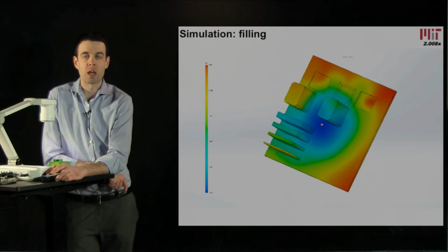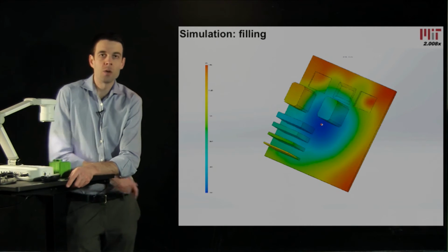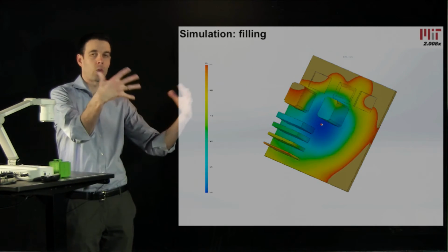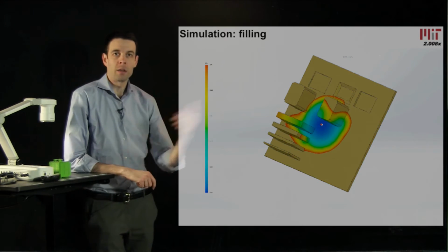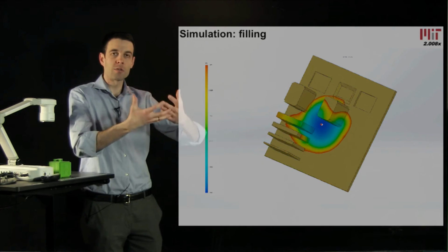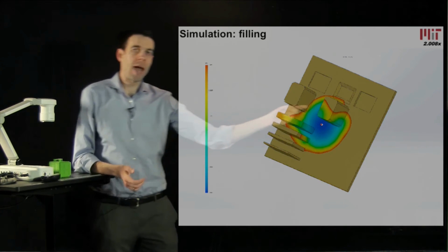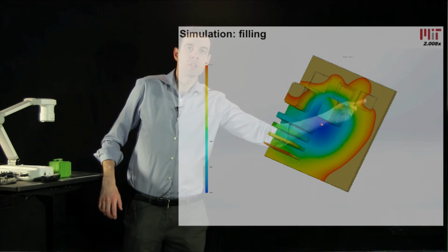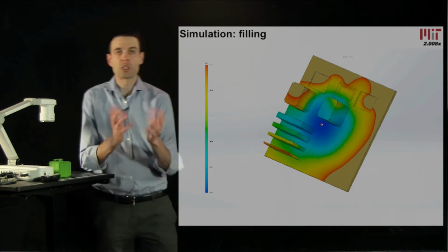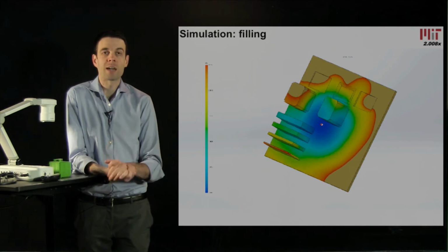This is once again from SolidWorks Plastics, and if we can start the video, you'll see the plastic flow beginning at the middle and flowing outward as we would expect. But we're just looping the simulation here, and you're seeing the dynamics of the flow are related to the local thickness of the part. And namely, the last location on the part to be filled is the 25% thickness area where we saw the void. So I haven't adjusted the simulation conditions to capture the short shot, but it's exactly as we would expect.